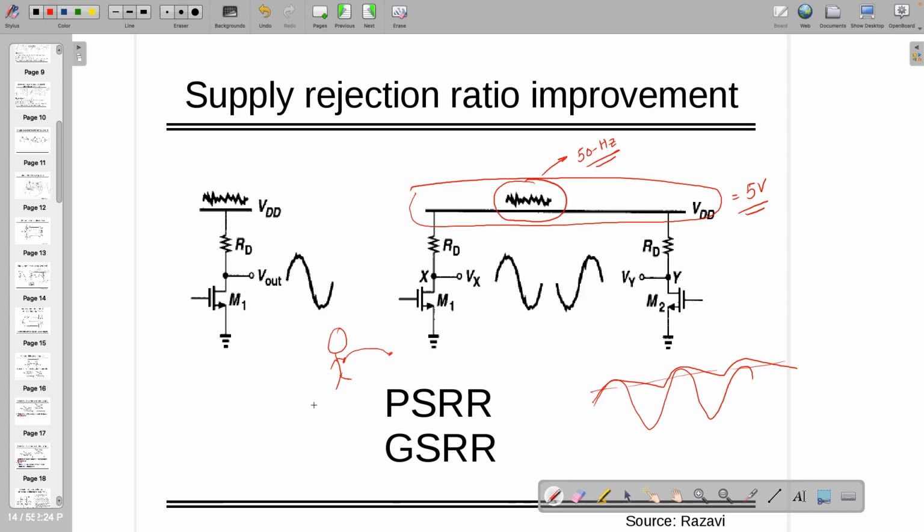Let's say some train is going outside, it has some frequency that will also act as a possible frequency source connected here, right? So all those things will give you so many problems. And understand, when there is a frequency, it's an AC signal, right? It's no longer DC. So you can say that VDD is nothing but the pure VDD with some noise.